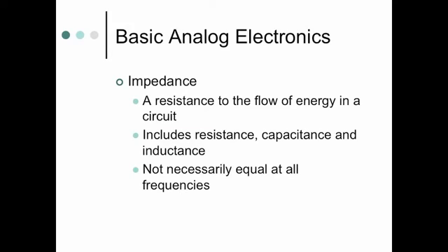Okay, so basic electronics. Impedance is the resistance to flow of energy in a circuit, very similar to resistance, except it has to do with different frequencies being treated a little differently. Capacitors would be considered an impedance source, and inductors, we haven't discussed what they are yet, but there are components that are frequency dependent. And that matters to us because once we transduce a sound from the acoustic domain through a microphone into an electronic signal, it has a spectrum, and that spectrum goes up infinitely. So the higher frequencies being treated differently, just moving through a cable or through a piece of electronic gear, will actually affect how it sounds at the other end of the chain.